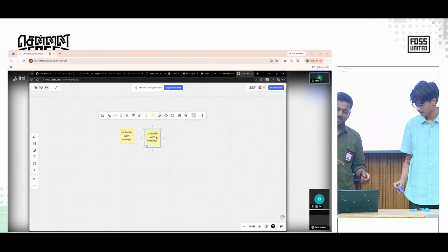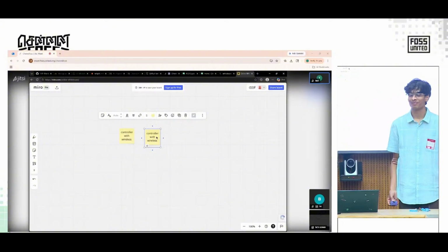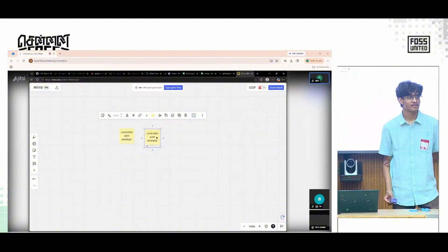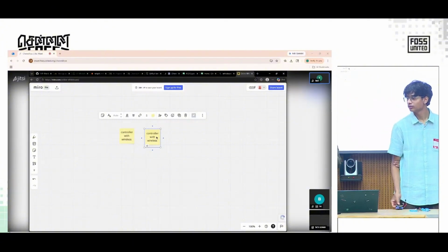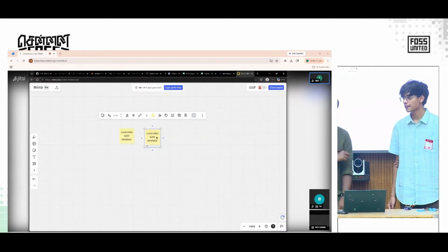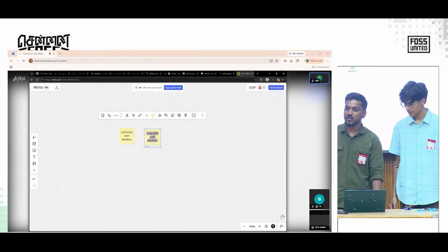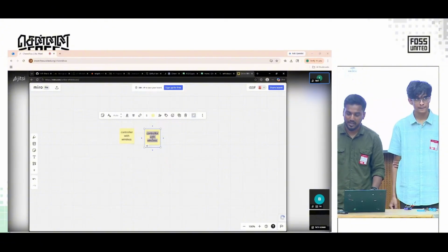But what we did was, last night we sat, removed the motor, and cut the communication so it doesn't do only 180. Now all the servos that you have have had some sort of modification done, so it does the entire 360. If you say front, it goes clockwise, and if you say back, it goes anti-clockwise. That is the reason we avoid using a regular motor and go with the servo motor, so you don't need the motor drivers.